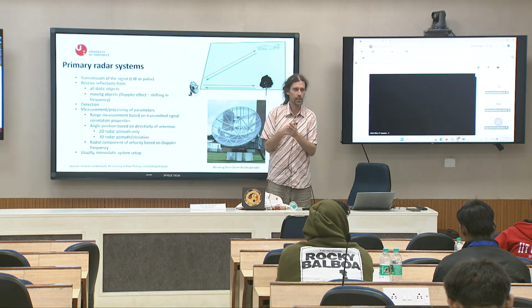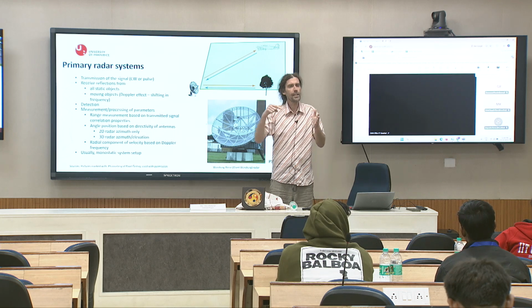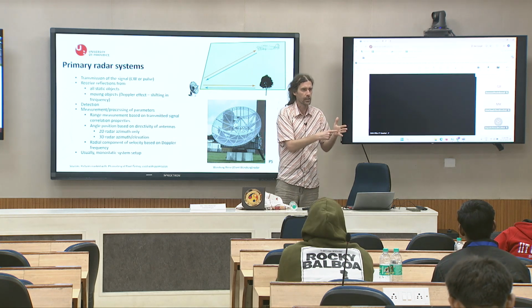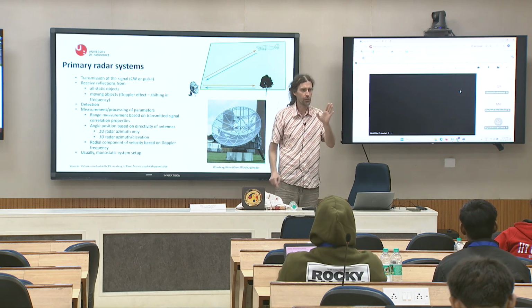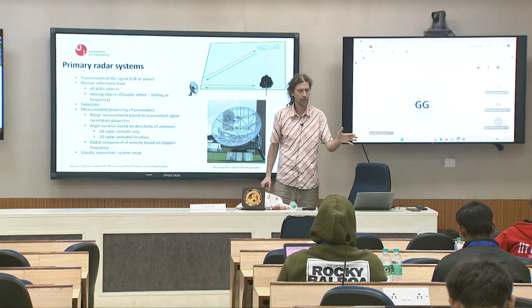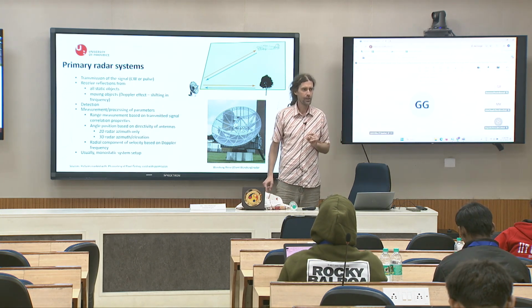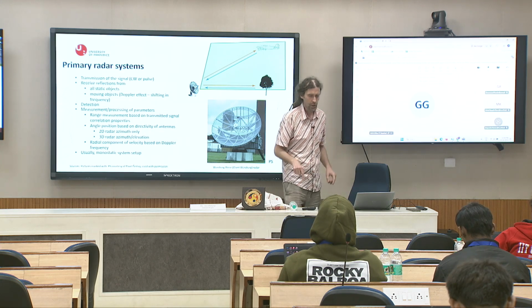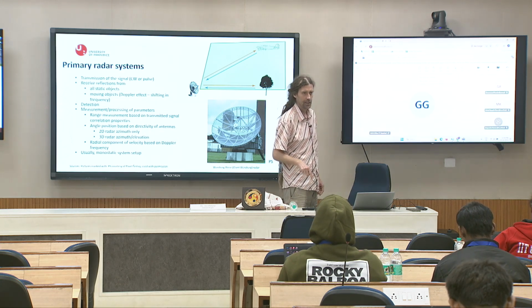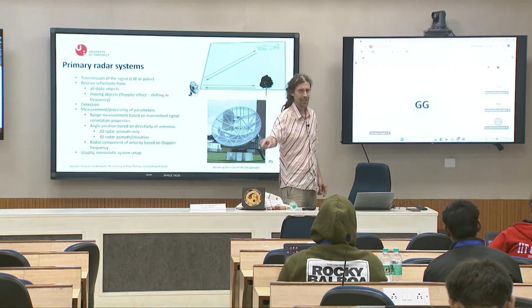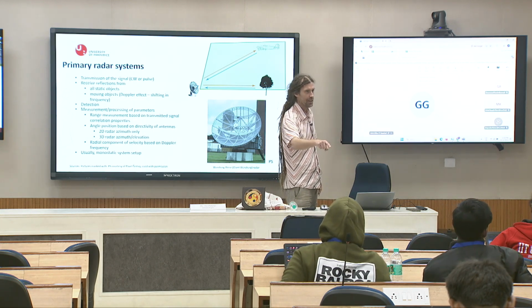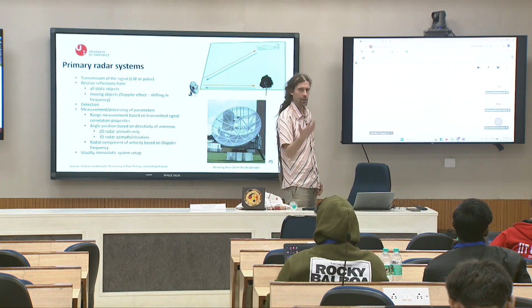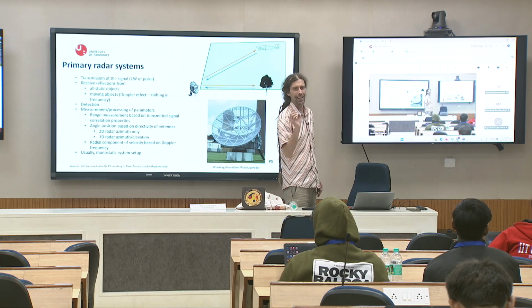So you can imagine what is included in the received signal? Reflection from everything. And now, in real time, you need to decide: is it a target, not a target, or reflection of the environment. We call reflection from the environment clutter.